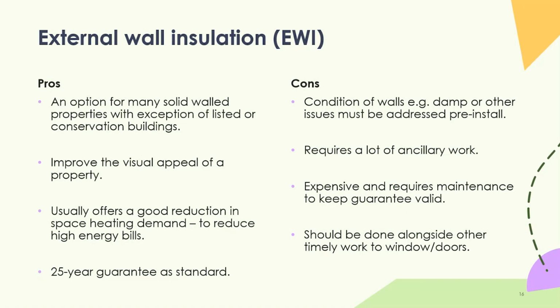The cons with this particular solution: conditions of the walls and other damp issues must be addressed before you install, obviously, otherwise you're trapping those issues within the insulation layer, particularly anything to do with damp or water intrusion, rising damp, or any other issues maybe to do with rainwater goods or leaking pipes. That must be sorted, and you must allow the wall to dry out before you start introducing solid wall insulation. So it does require a considerable amount of ancillary work.